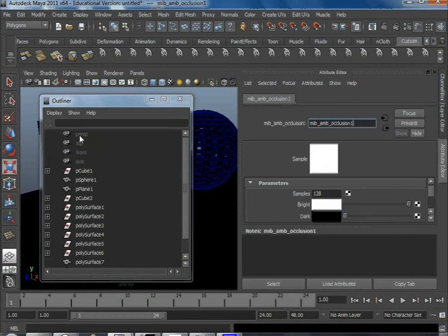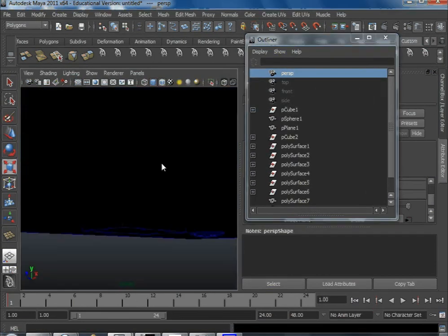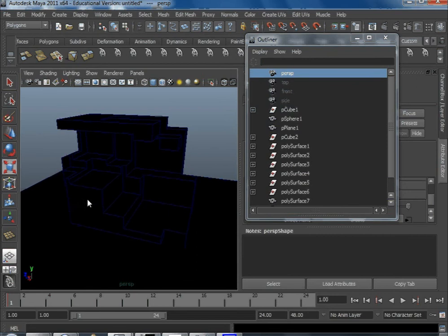Here's what I will do first. I have a camera, right? I will select my camera and then use S to keyframe the position. It's very tricky, actually. If you don't do that, by accident, you will move the camera around, right? If you do another rendering, it does not match. This could be a problem.